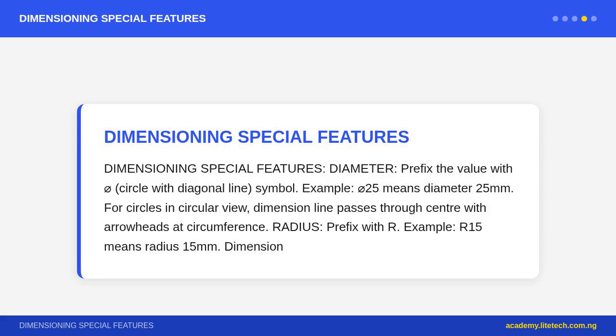Title block. Every engineering drawing must have a title block, usually bottom right, containing drawing title or component name, drawing number, scale, e.g. 1:2 or 1:50, date, drawn by, checked by, approved by, material and finish specifications, company name, sheet size, A2, A3, etc.